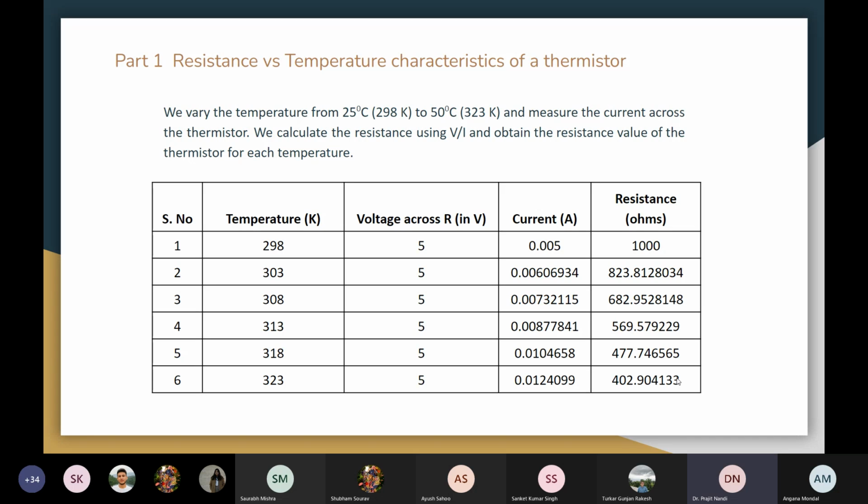But the key thing to note is that during power up, things are not under our control, meaning the power supplies can vary widely. So as designers, we take a lot of care to ensure that when the circuits are powering up, it does not create device failures. A circuit designed to take current in milliamperes in the steady state should not start taking currents in amperes while powering up, because then the power supply is going to be messed up big time. So we need to ensure these key things,